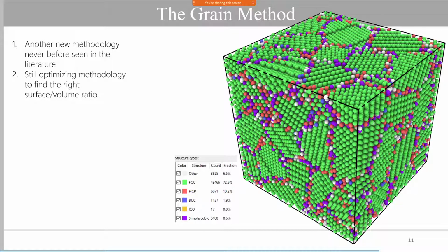And the idea here is that we create a stupidly big lattice and create grain defects inside of it, as you can see in this picture. So notice how the different FCC structures are aligned differently and are joined by grain boundaries which are not in FCC. The idea here is that those grain boundaries will make it so that the melting temperature will be lowered.